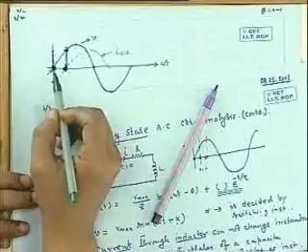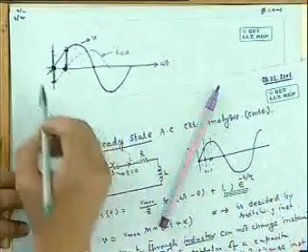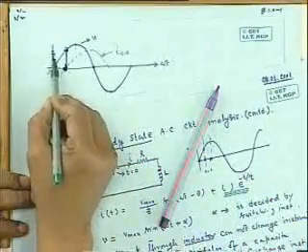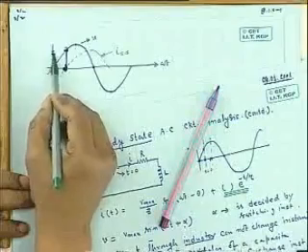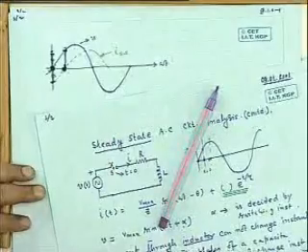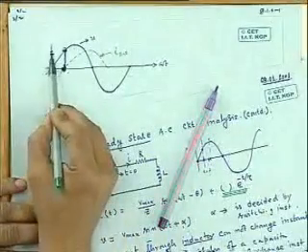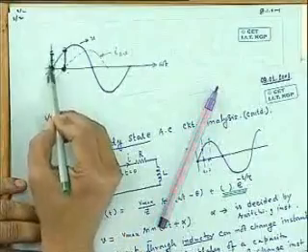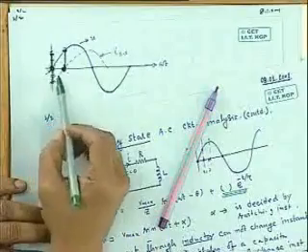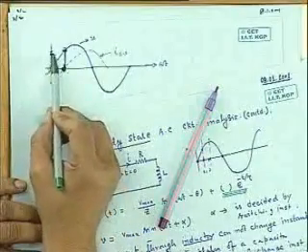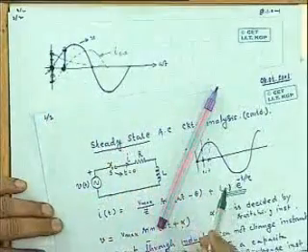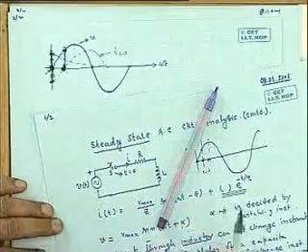I am trying to give you a physical interpretation of that solution. What is this? That is this current, this length you cut out here. This much current has to flow at this point of time in the opposite direction, such that this condition will be satisfied. However, there is no voltage to sustain this current. AC current will be sustained by this one. So this current will decay down with its own time constant decided by the L by R ratio of the circuit.